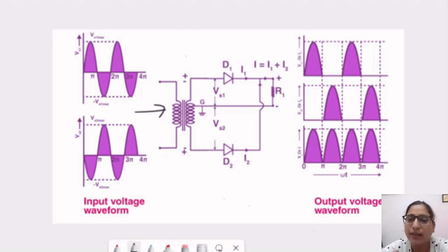Now, we know that output depends on the number of coils inside the transformer. So, we are using a step down transformer here. Why so? Because at input we are getting high voltage peaks and for diode circuitry we need a little lower voltage. As an example, I can say that the coil ratio in this is 10:1.